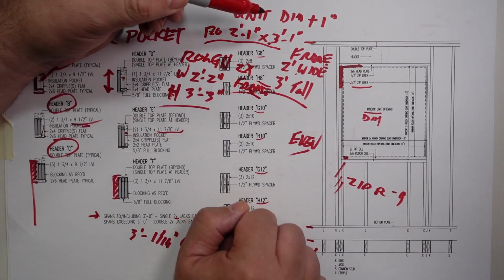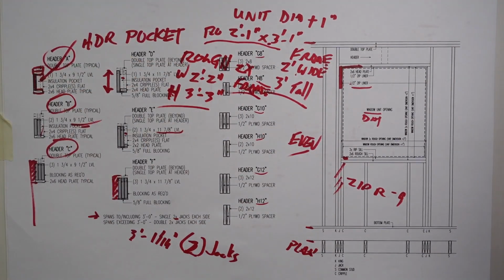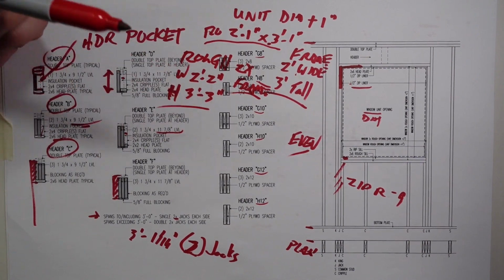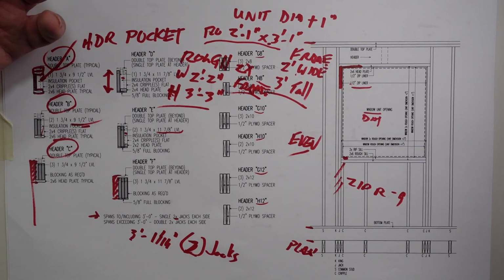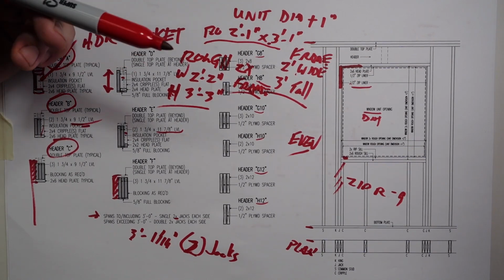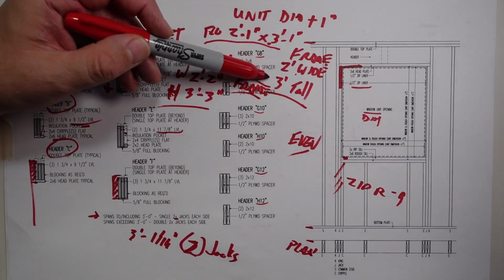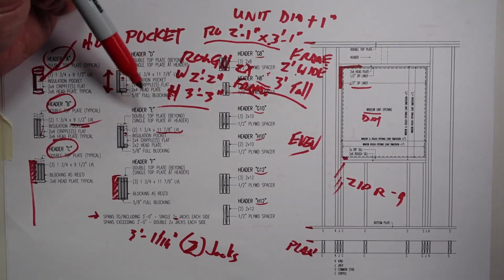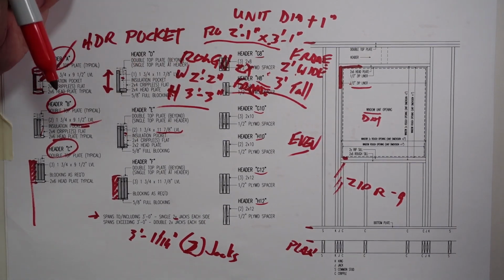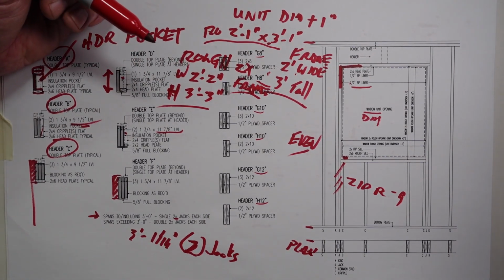But understand that putting that window in, it's imperative that we get this information to the framer, so that he's not always asking, well, what are the ROs on these? What are the rough openings? You don't want to give him a rough opening that's unit dimension plus 7/8, and then this one is 1 1/16 inches. So he's doing all this crazy math.